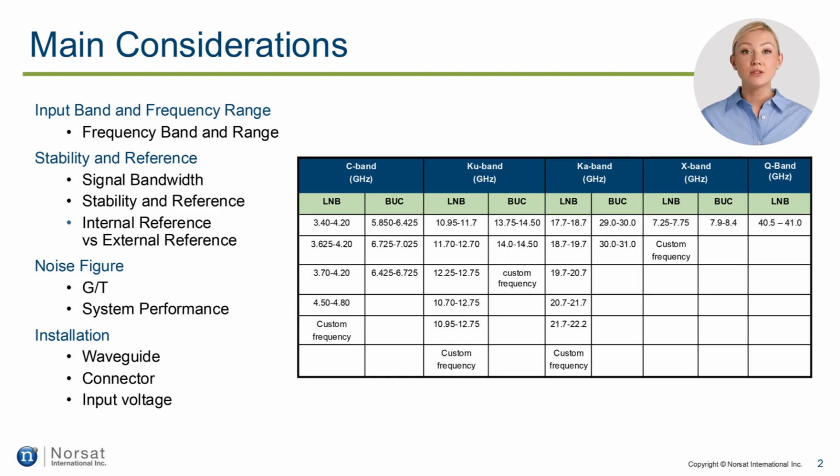In the previous chapter, we mentioned that the LO stability can sometimes be found in specification sheets as ppm, which is the variation ratio over the LO conversion frequency. Keep in mind, it is a different expression of the same content. The next important parameter is the noise figure, sometimes also called noise temperature.